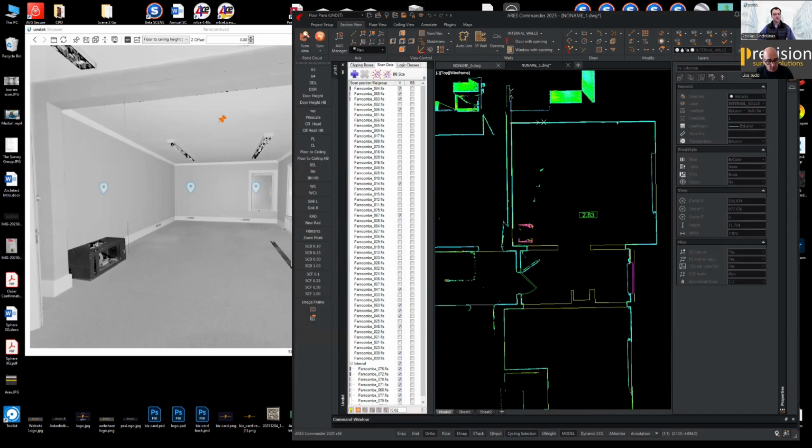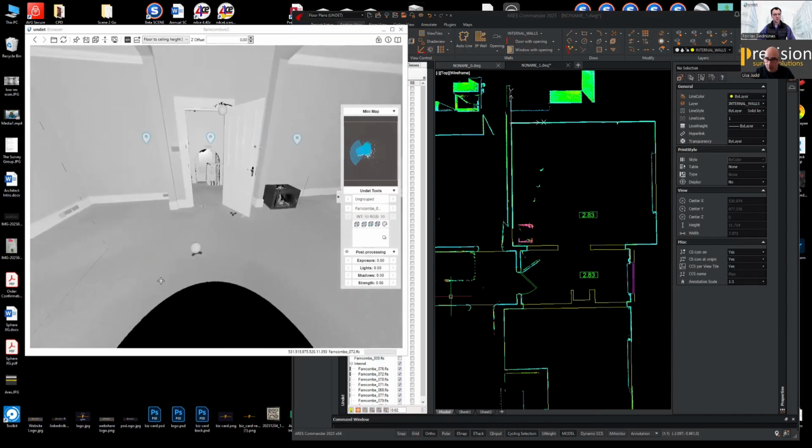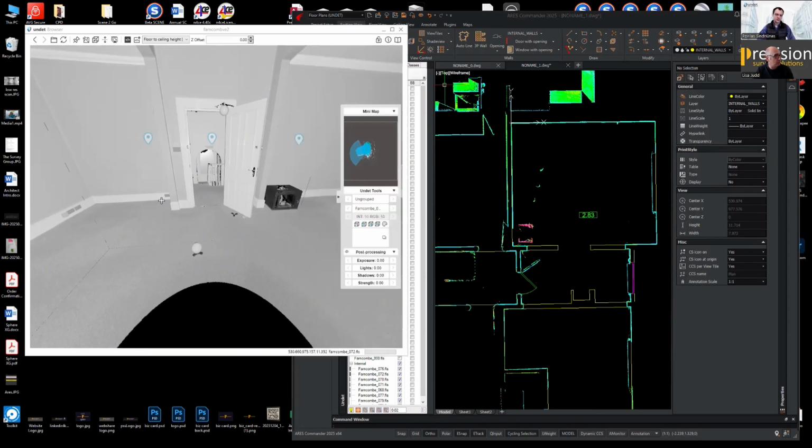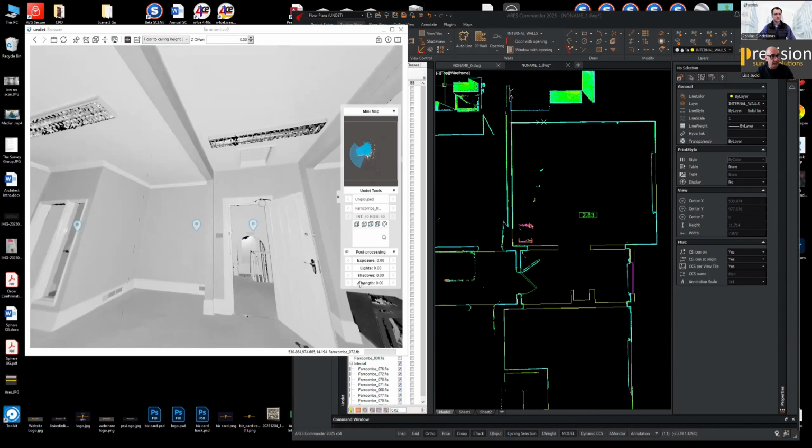And the usual way that we would have done prior to browsers and things like that is we would have said, right, well, we'll now copy that to the next room. We go to the next room and we ask for what the floor level is and we change that information. That again is where, if somebody phones and you've copied it and you haven't changed it, you've forgotten about it, you've now got inaccuracy in your drawing. So to add automation means that with the scripting on, we can say floor and ceiling and we get a floor to ceiling height automated. Okay, if it's in there, it's been done automatically.